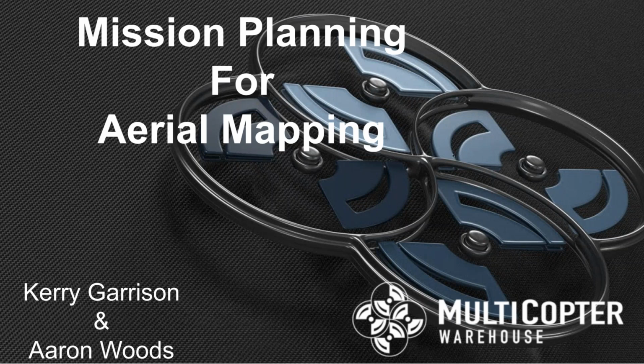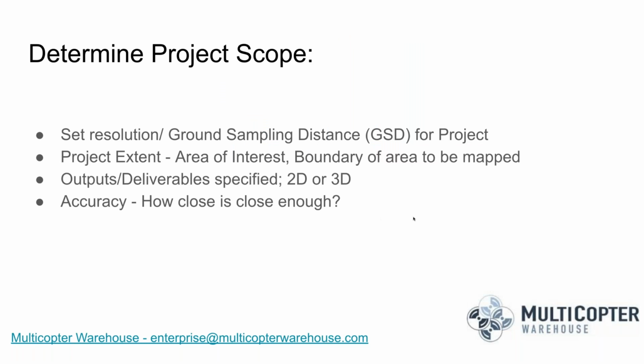So we're ready to get into this now? Sure. Whenever you're thinking about mapping, there's a few things you want to get settled ahead of time before you dive into a project very far. The first item is you want to determine your project resolution, or ultimately what's called your ground sampling distance, or GSD, for that project.